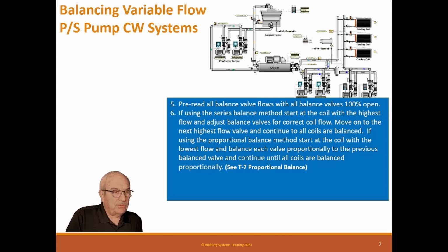But when you start with series, the first two valves I would balance down below design a little bit, because as you balance the others down, it's going to push that water back up. So you want to keep balancing down, and you have to get a feel for it, and over time you'll get used to how to do this. As you keep going, keep looking at your target valve to see where it's at. When you get about halfway down, if you have small valves, you can just balance those down to design flow. You don't need to go down a little bit more.